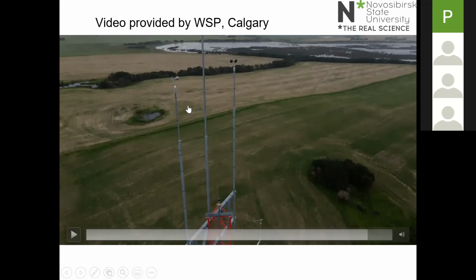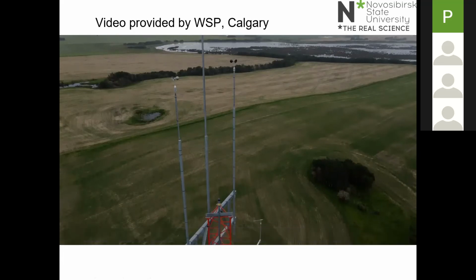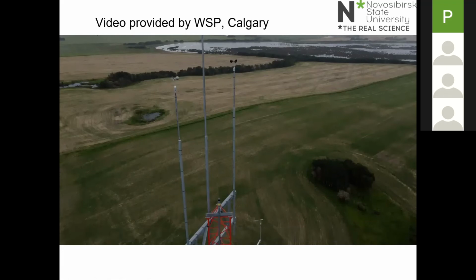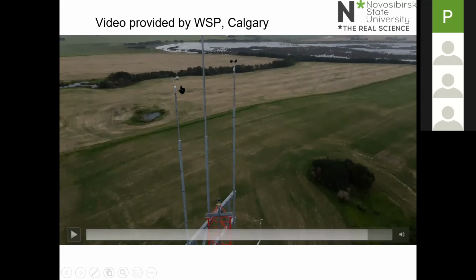Now, an anemometer mast, if it's 80 meters high and you want to rent an anemometer mast for a wind farm project, that will cost you about $50,000 a year. Okay, they're very expensive. One of these anemometers costs about $1,000. So the actual measuring equipment is a very small fraction of the total cost of the mast. And so duplicating the anemometer is cheap.